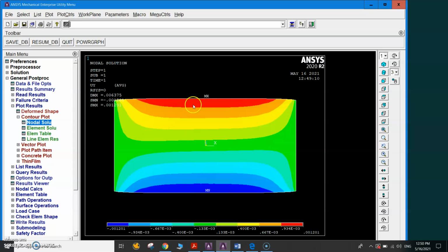So the next step, this is the total procedure to define multi-layers for a plate, and then you can do the same procedure for a plate with cutouts, and you can, for example, investigate the effect of different cutouts, for example, circular or square cutouts or rectangular cutouts as well. And then here you can plot the results and see how much is the maximum stress, how much is the maximum shear stress, and other parameters, or von Mises stresses. You can watch them here and compare the effect of different cutouts on this plate.